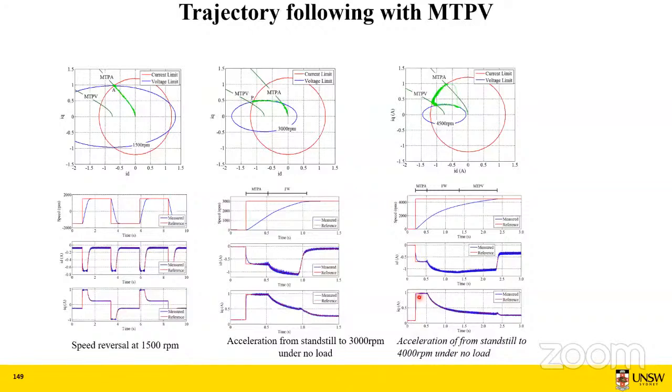Similarly, the Q-axis current has a very similar characteristic to the torque. As I said, the torque and IQ current profiles are exactly the same. It was maintained at 1 ampere, and then in the flux weakening, the IQ current starts to drop, and then it settles down to whatever the load demands at steady state.